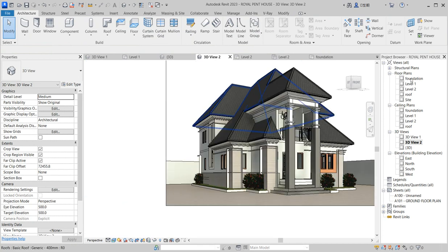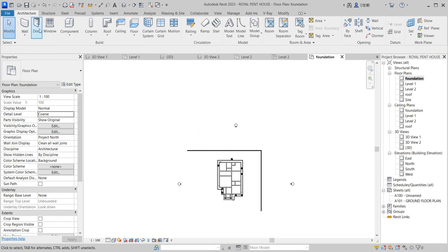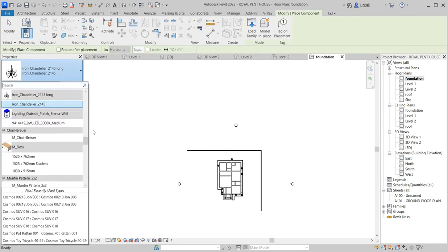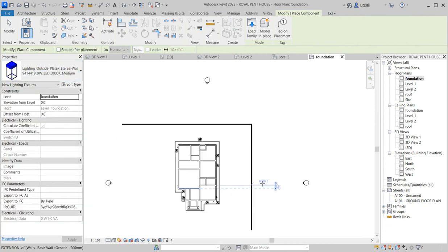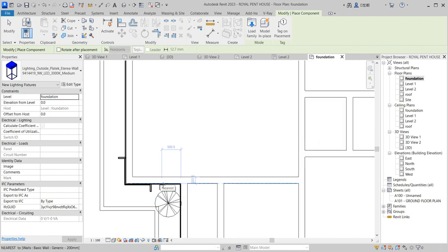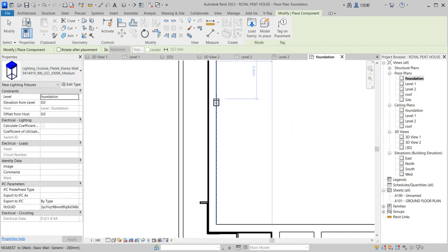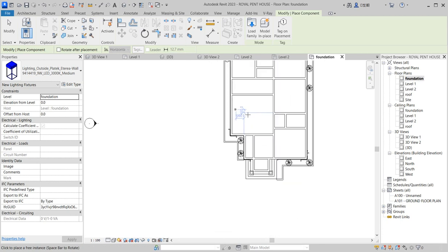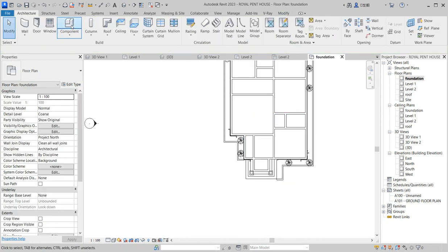What you need to bring down is some light into this place. So let's just go to components. What you do next is you click on this one, it's supposed to be here. Bring some light into this position right here. Select that. It's supposed to be on level 1, but it doesn't matter whatever you set up your light. You can select all instance and raise it up later, as that's what we want to do. So that one is there.